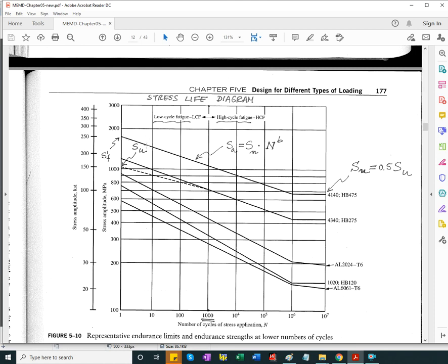We have this regression line that's sloped and then moves horizontal, and this is one material: medium carbon steel, low carbon steel. For aluminum, past 1 million cycles, the curve reduces slope but doesn't stay horizontal. So aluminum doesn't actually have an infinite fatigue life, something that aerospace engineers know. Aircraft structures have certain maximum numbers of hours of life assumed for them.